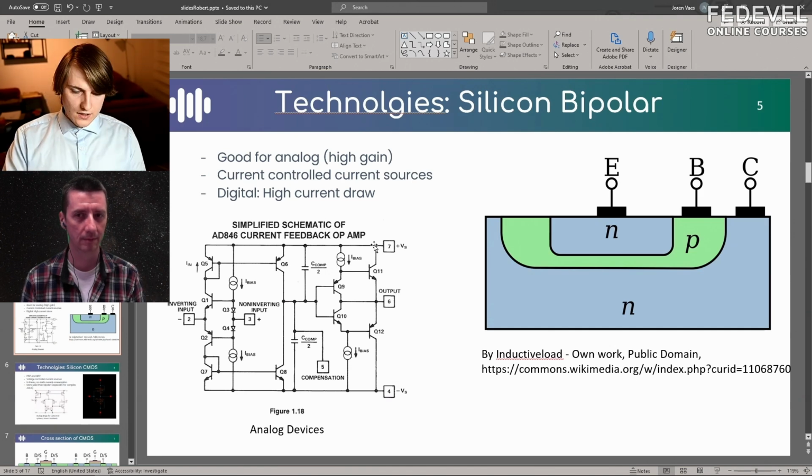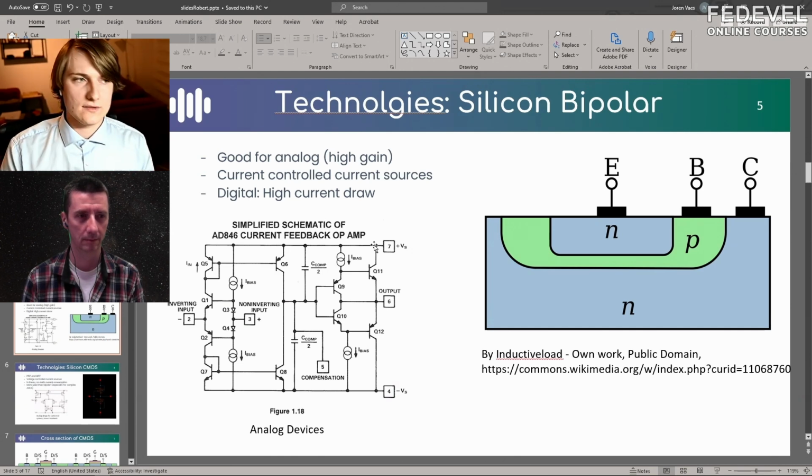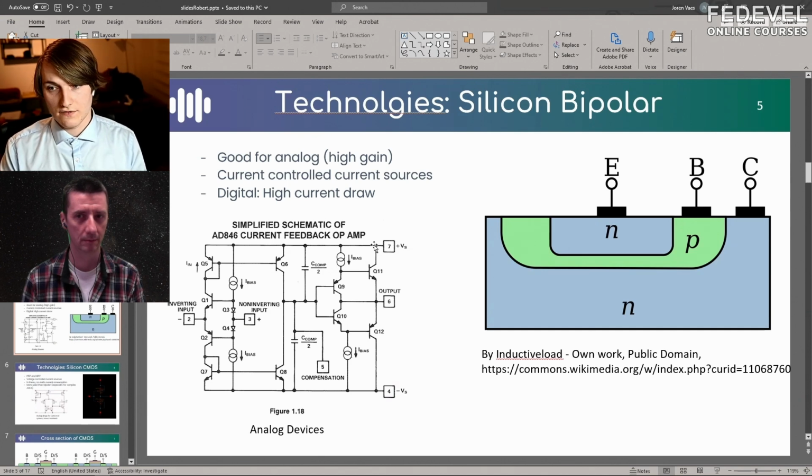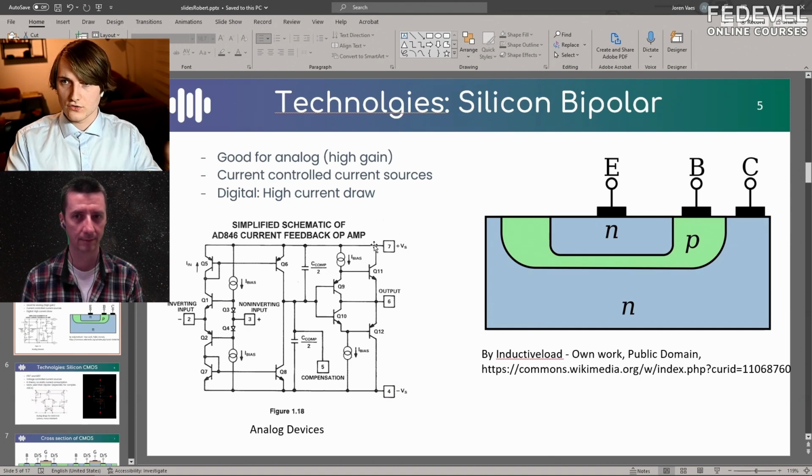What you do see is what they call BiCMOS. That's when you have a CMOS process and they add bipolar transistors, or you have a bipolar process and they add CMOS transistors. That's often used. For example, Infineon has a very famous, very high performance BiCMOS process with extremely fast bipolar transistors that work up to 500 gigahertz or more, and a very basic CMOS technology. So in your RF or automotive radar, you can implement some digital control circuits to control the entire thing. That's something you do see.